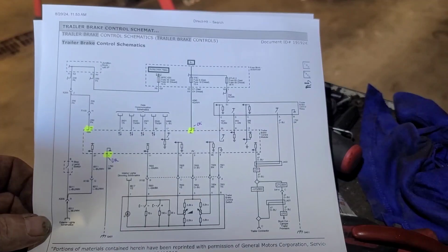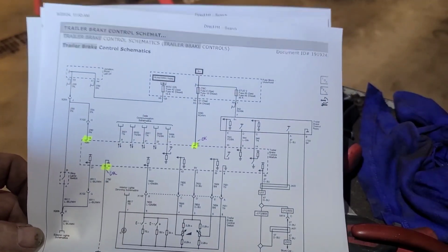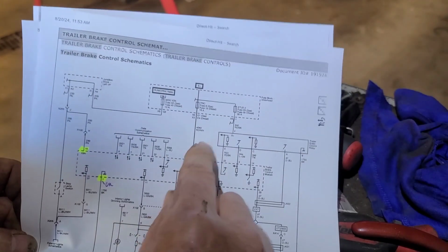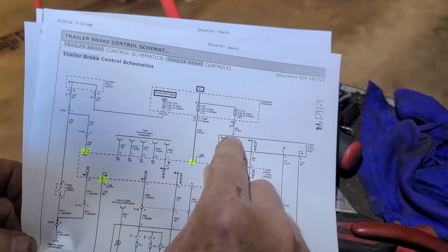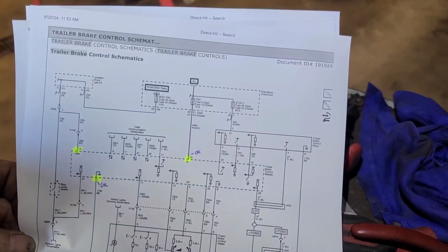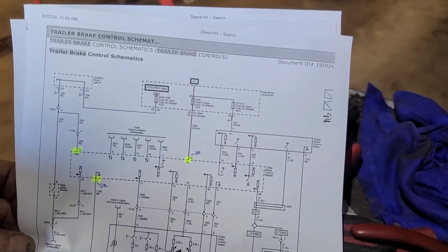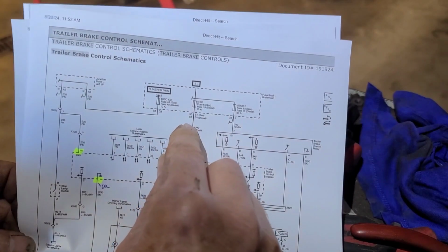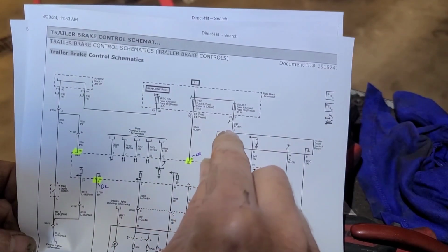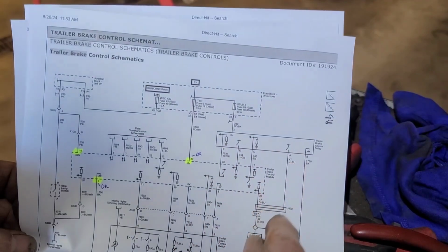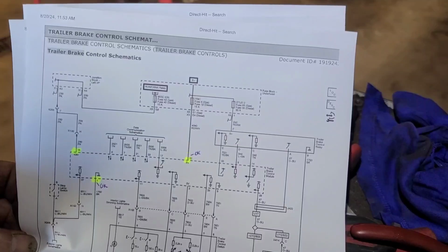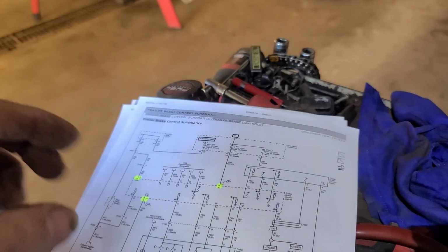So that's the trailer brake control relay. It's some kind of electronic relay. It has power from the same circuit as pin 32 on this one. The red wire comes from the same. It comes from feed stud 2. This one doesn't show which feed stud, but it's the same. Well, we're going to check that power and this ground. Red with a black tracer and black.